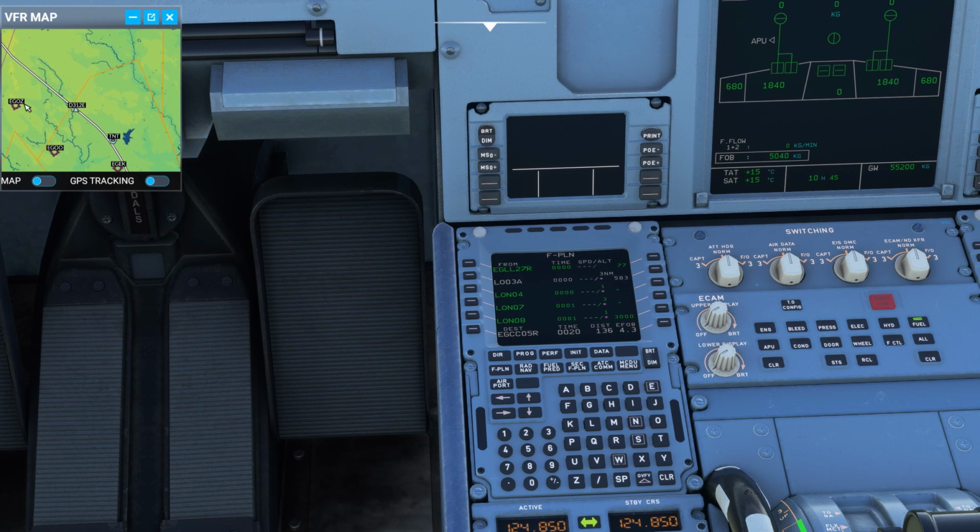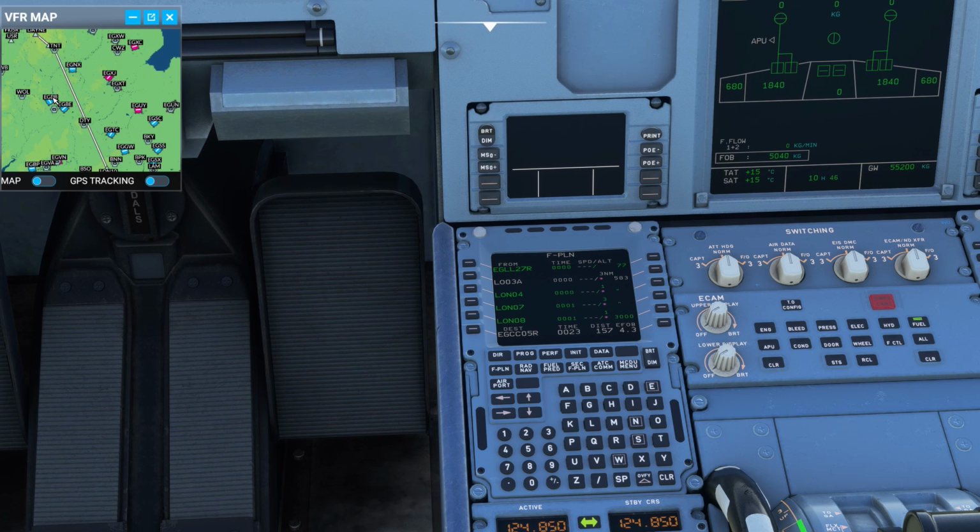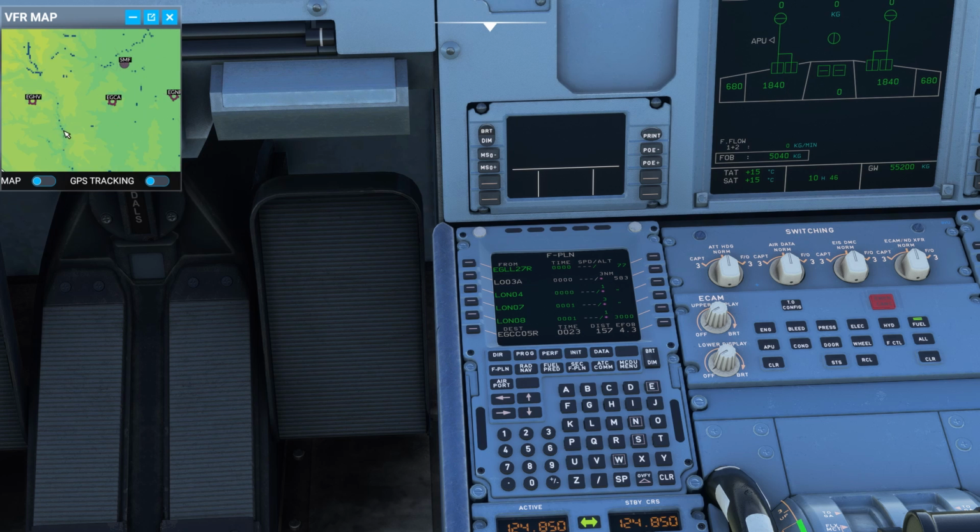Okay, there we go. It's chosen its route. Now, by doing that, I've now also got the TNT waypoint that I wanted in there as well. Okay, so I've got umlaut, which I had, and I've also got TNT. So that is 2 waypoints already that I now don't need to enter that I had before. So this is why entering the arrival and the departure before you take off is, well, the departure definitely, but the arrival before you take off is beneficial because you may not have to enter the rest of the flight plan. Okay, so that's now entered.